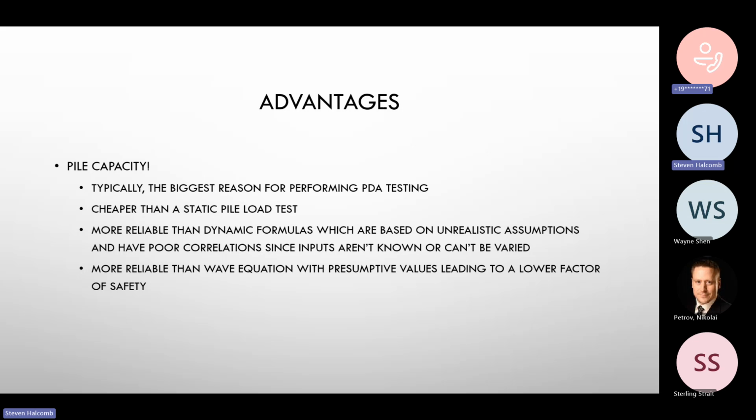And we can, like I said, match that wave. We can actually measure the wave. We can go back to the office and go through the math, change a bunch of variables to dial in what our pile is experiencing at that moment in time, which is a huge benefit. Maybe a con is that it can take a little bit of time to process that data, usually a couple of hours or so, but it's definitely faster than a pile load test, and certainly more certain than a wave equation.